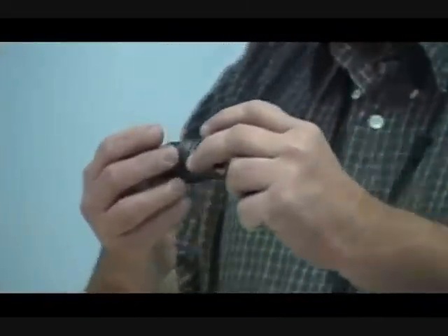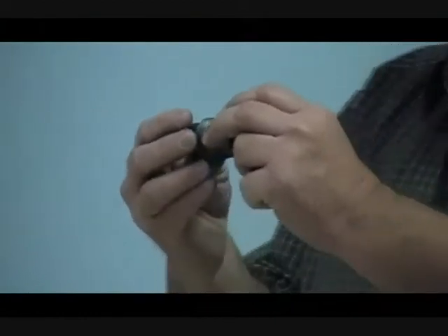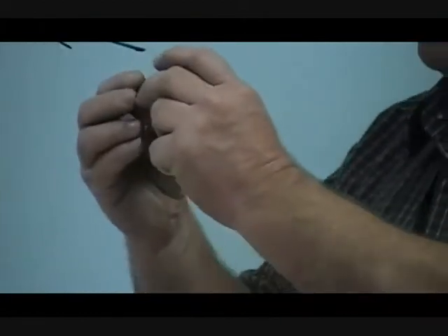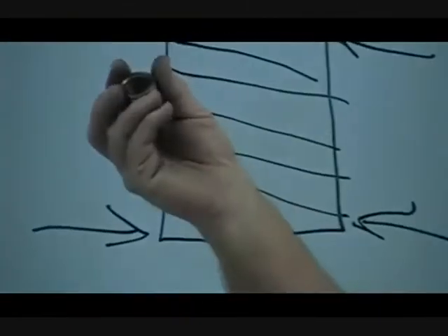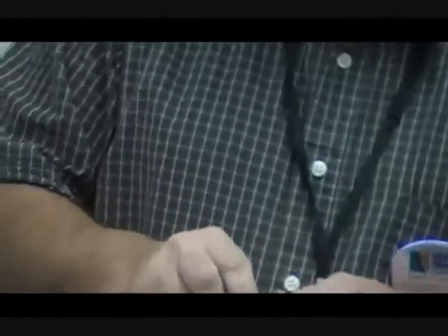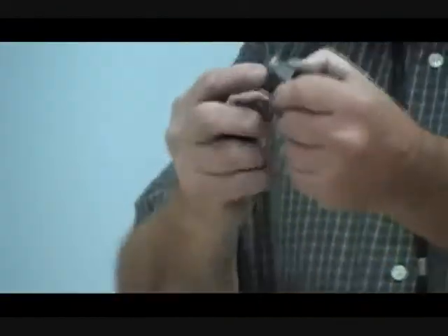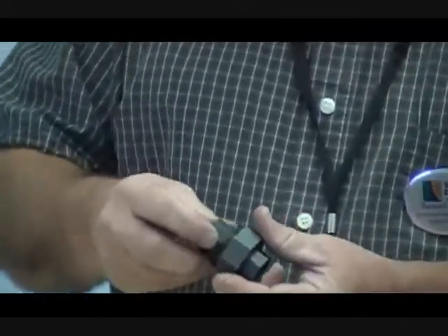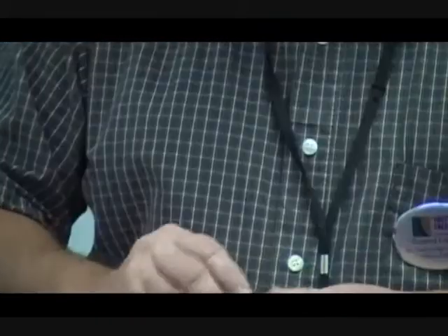They may come out of the same box, but they have been mated to one another, okay? They've been lapped in, what they call lapped. So if I use this from another fitting, maybe the same mate, maybe the same everything, but it's not going to tighten up correctly. Now you would not use any joint compound on this part here, okay? Only on the threads.